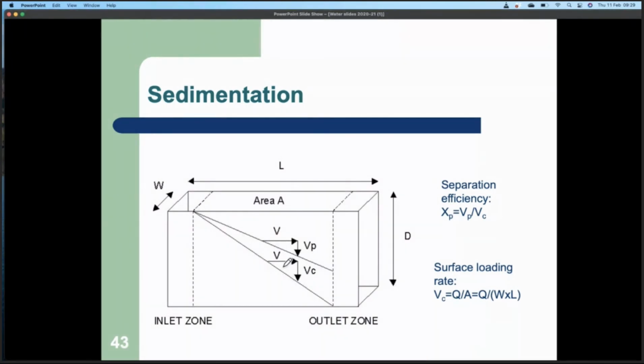When you go and see one of these sedimentation tanks, it does appear as if the water is standing. You don't actually see any movement of water with your eye, and that is simply because the plan of the whole tank is to keep the velocity of the water as close to zero as possible, so that there is A, no turbulence in the tank, and B, the water stays in the tank for longer so that the particles have more time to settle to the bottom.